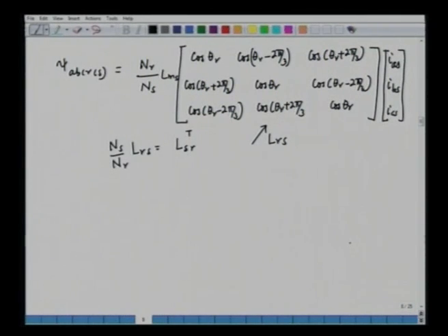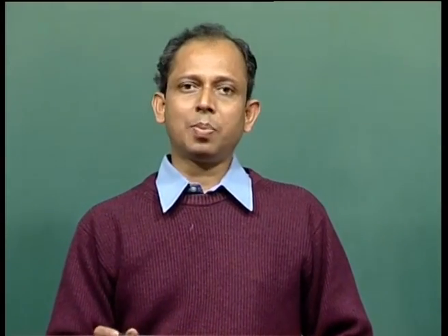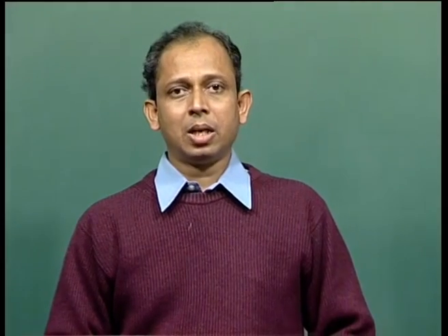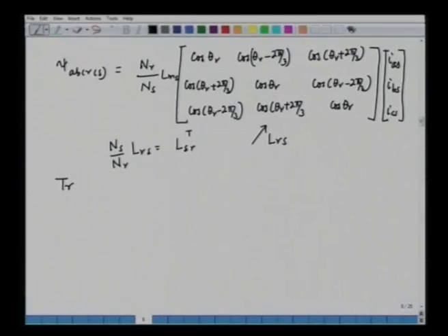Okay. So, these actually are the equations in the actual machine variables, IAS, IBS, ICS, IAR, IBR, ICR. But very often whenever we have a machine, we would like to refer everything to the primary side, that means to the stator side. All the parameters that we have in an equivalent circuit are also referred from the primary side. So, there is a need to transform all these variables to the primary side, which is the stator. So, we can see the transformation to the stator side.